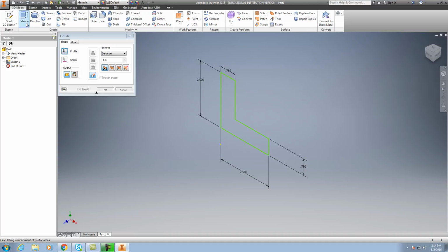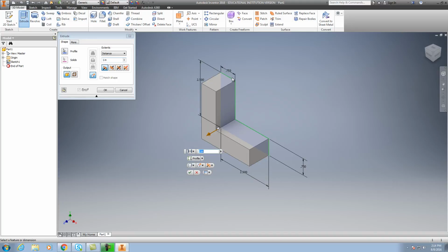Click on it. Now, it automatically picked it up. You see that 2D sketch we made? See how it's trying to add that solid to it? Well, make sure whenever you draw this 2D sketch in that you have no open loops.